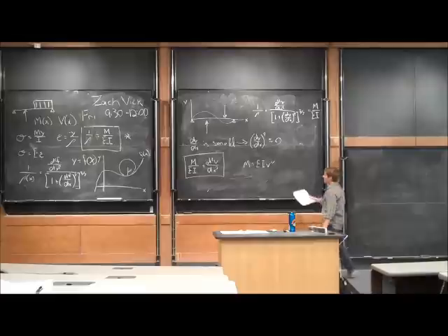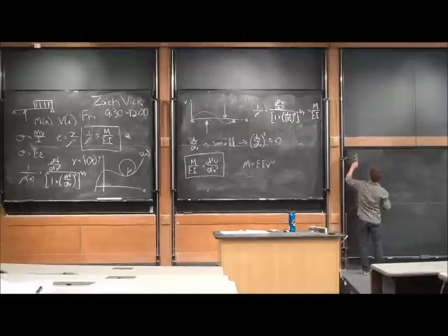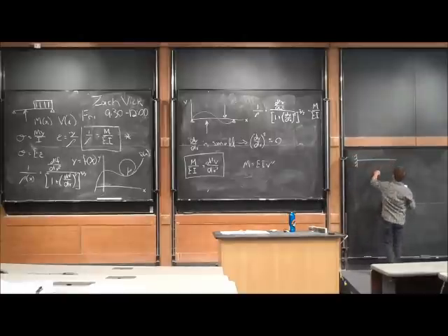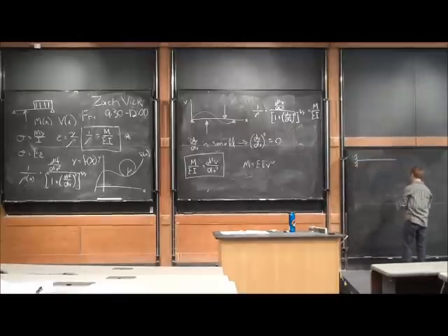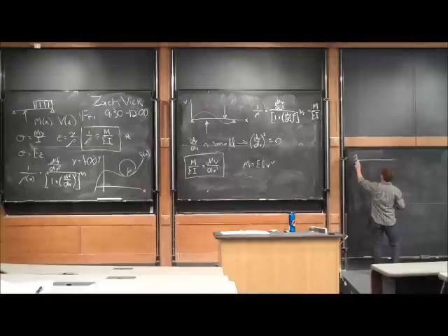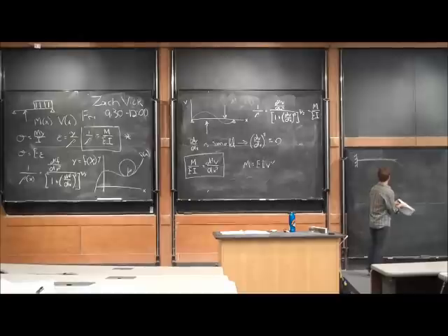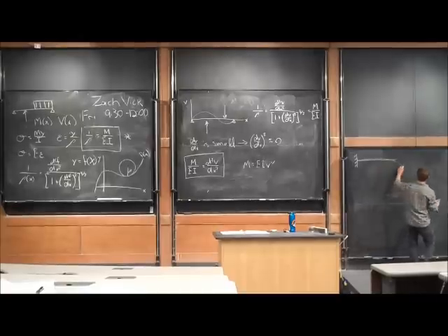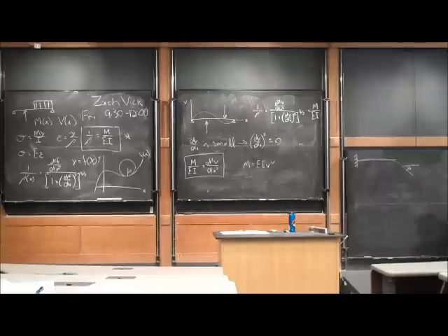it is going to be the slope of the beam. So if you think of a cantilever beam, when we put some load on it, it'll deflect, something like that. If we look at the end of this beam right here, we have this angle theta, and that theta is going to be our value of the slope at that point.